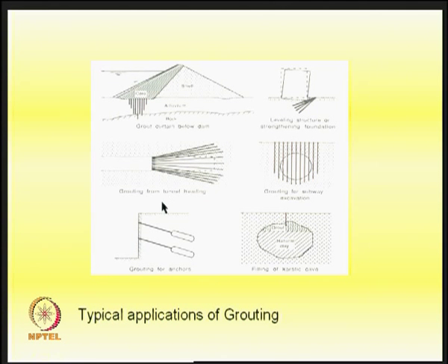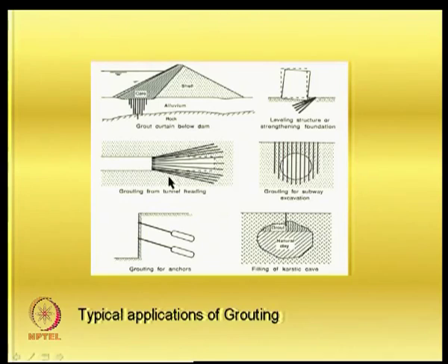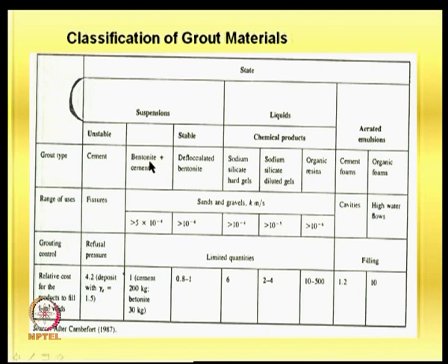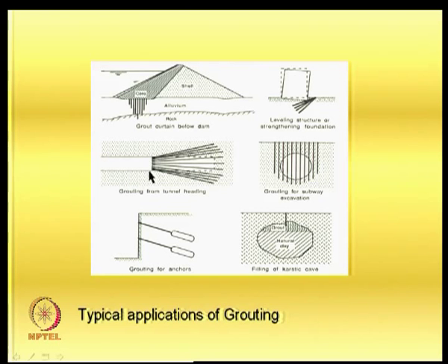Another one is that you are trying to make a tunnel here, suppose a water tunnel, subway or underpass, and the area should not cave in. When you are putting in the tunnel, the front end should not cave in. So you grout this material and then complete this process, because otherwise it will collapse like this. That is a very risky operation. In some cases, grouting is also done for subway excavation, so that at least the area next to it is somewhat stable.